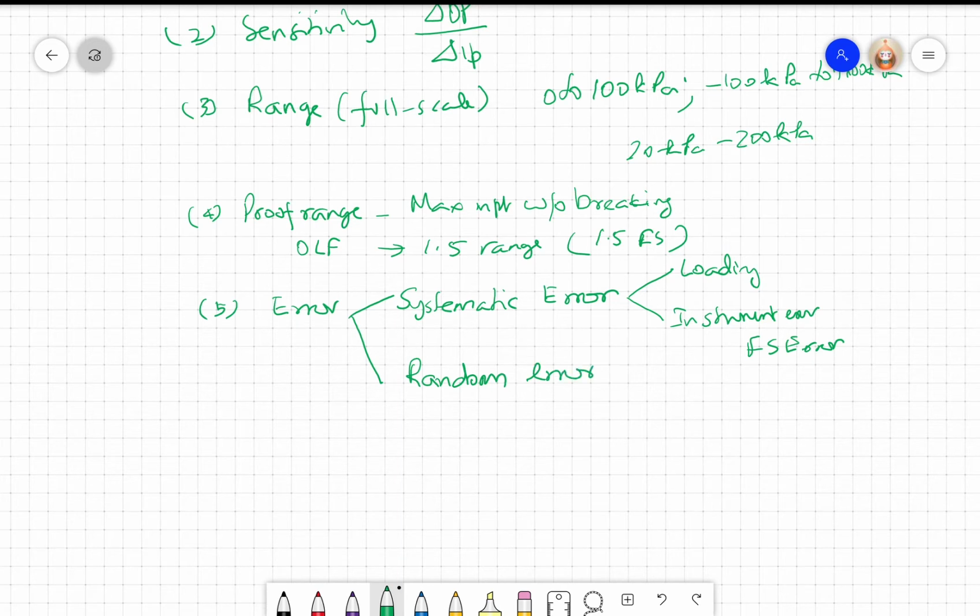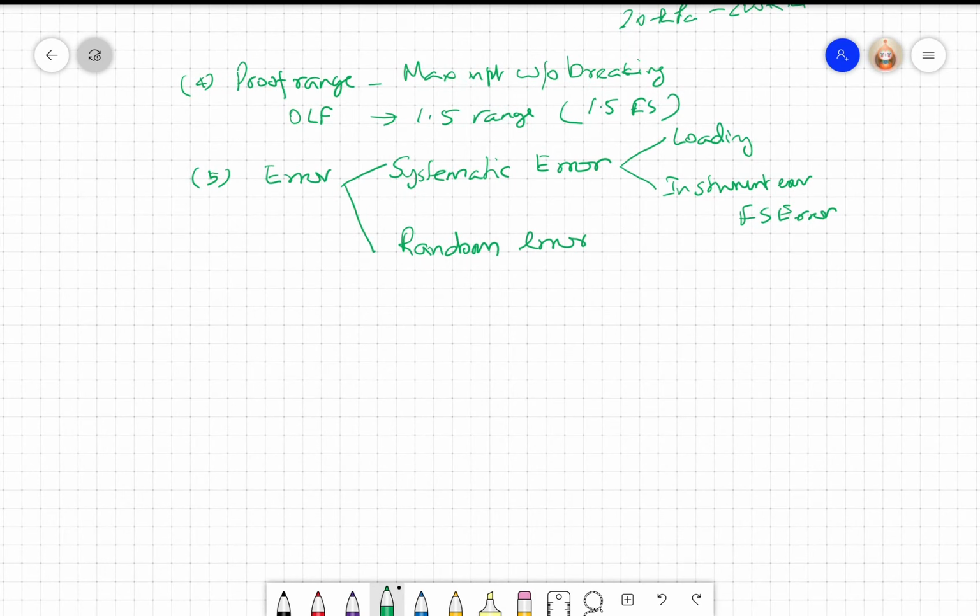The second one is the random error. Random error most of the time comes because of the inherent nature of things. We saw that even if I have a simple resistor, the resistor generates thermal noise because of the temperature, and that would be a random phenomenon, right? Whenever random error occurs, the only recourse is that we take multiple measurements of the same quantity and calculate the average value.